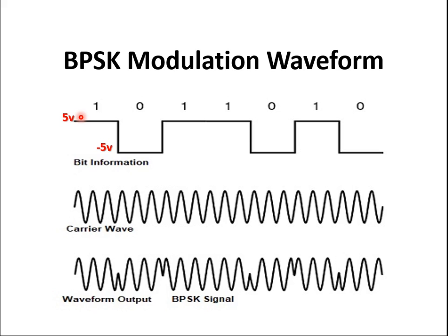Let us consider 1 volt only. 1 volt multiplied by this part. This is continuously varying, right? But this is constant like 1. This continuously varying carrier you consider as x, multiplied by this positive voltage will be my normal x only. You see there is no change in any signal from here to here, because up to here my signal is plus 1 volt only. This plus 1 volt multiplied by this x will give me x only.